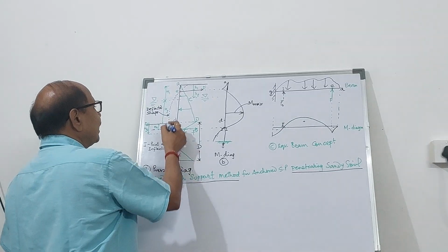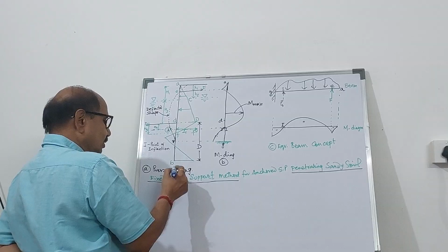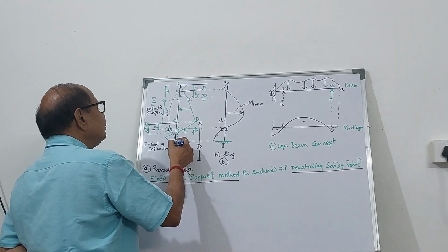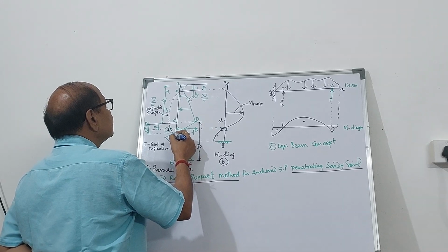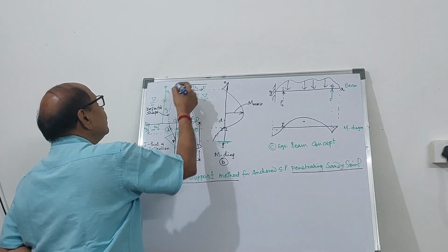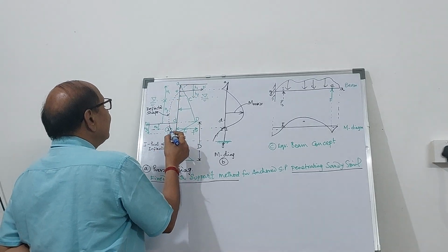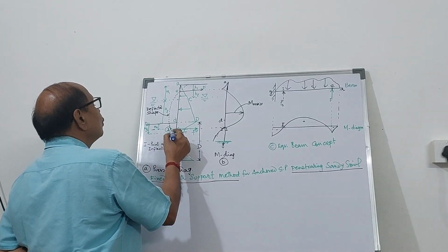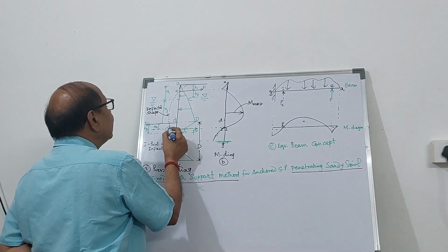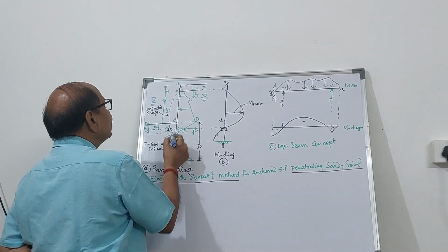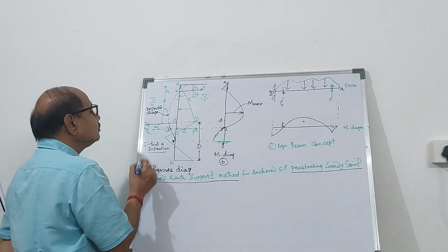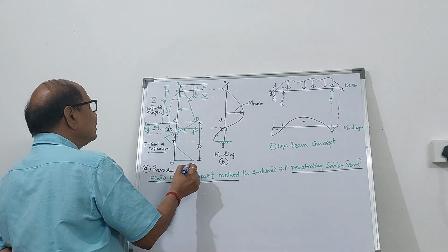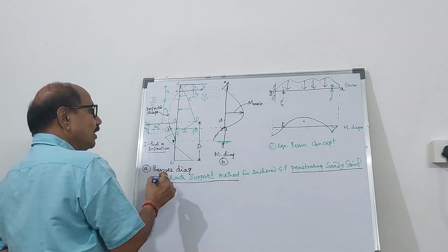If you see the deflected shape of the anchored sheet pile in the fixed earth support method, if you take it very deep, the deflected pattern is going to be like this, as shown in the dotted line. So the deflected shape of the sheet pile is shown by the dotted line, and point I is the point of inflection, and therefore the pressure distribution diagram has been shown over here.